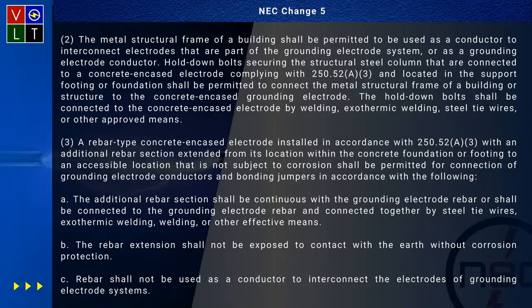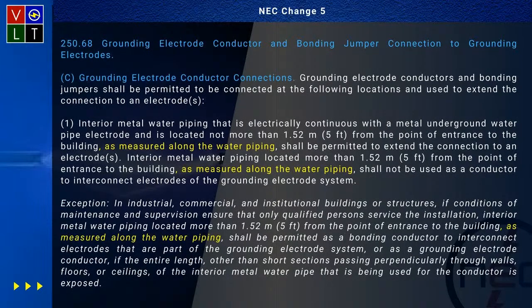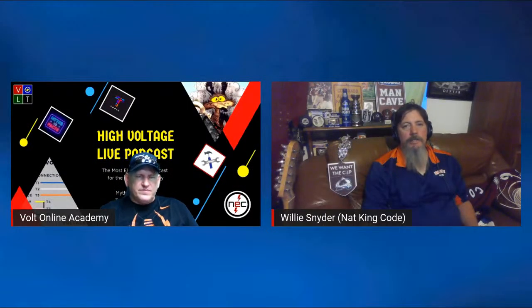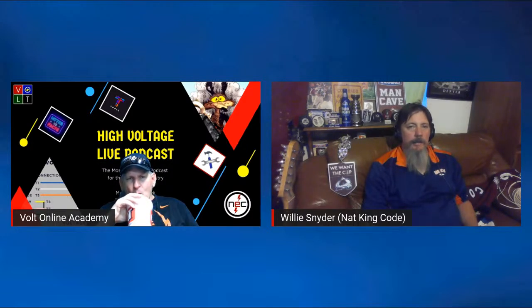I mean, I think all of this and coming back, changing this heading in 250.66 and adding the bonding jumper connection in here, this ties all this in where all the electrodes can be connected into a terminal bar, and then naturally it's going to be sized based on the largest conductor that's connected to it. Yeah, and so I don't want to put anybody on blast, but I actually watched Christine Porter do a thing on grounding and bonding, and that's where I'm taking my interpretation.